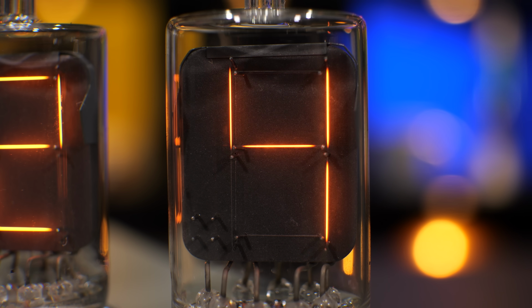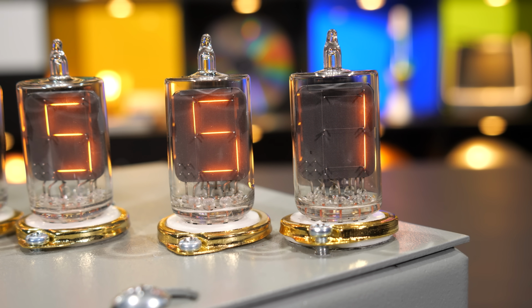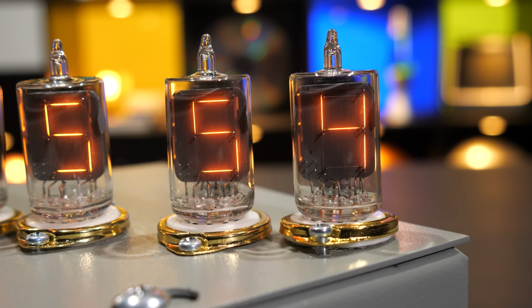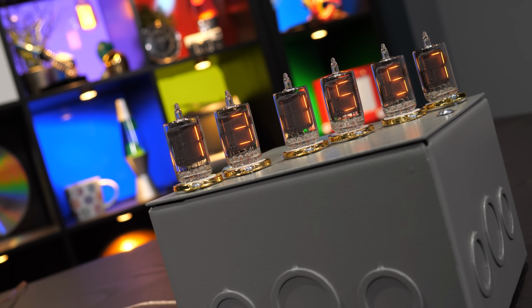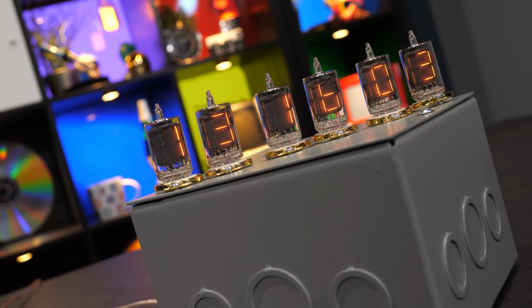And while today the use of incandescent filaments in a 7-segment display might seem objectively absurd, that was, in fact, the point. These tubes are dead simple and require nothing special at all to use. They only need 5 volts to glow, so they didn't need their own power supply. Incandescent filaments are self-regulating too, so there's no need to add current-limiting resistors to the circuit. And since they were so tiny, the segments only consumed about 25 milliamps each. This is actually the largest version of the tubes RCA made, but they don't even consume a watt of power with all the segments lit.